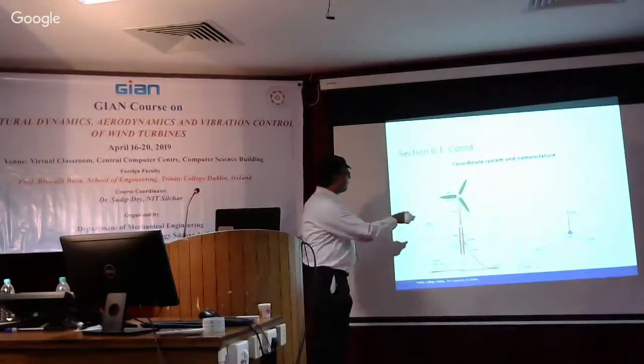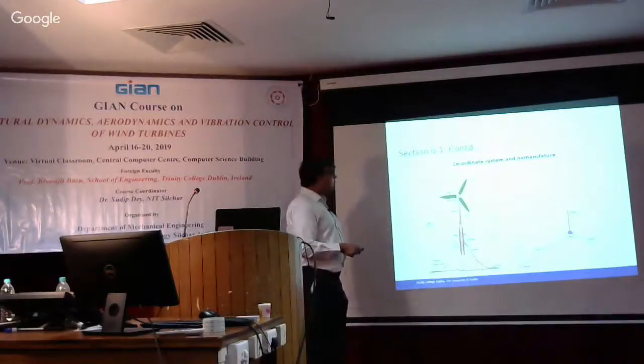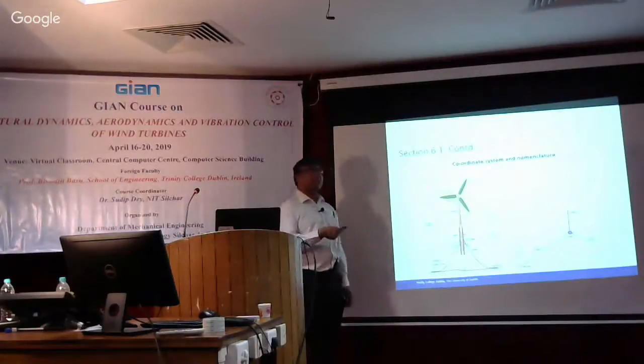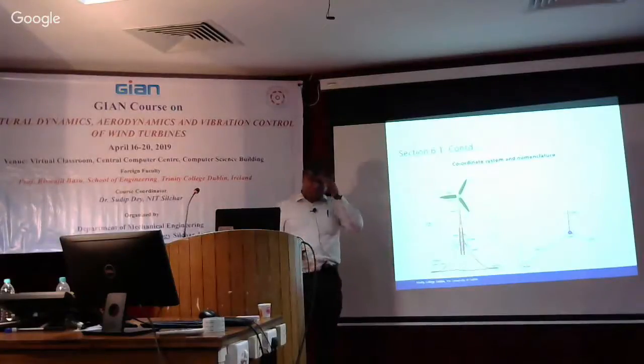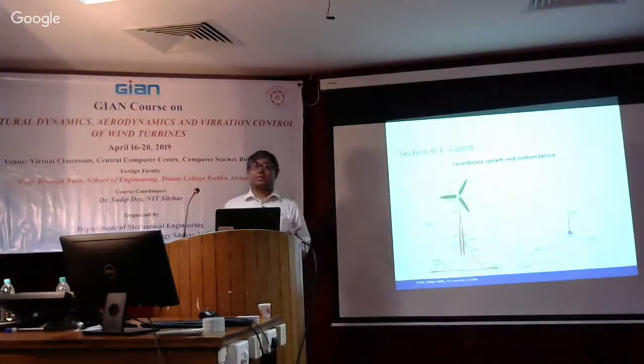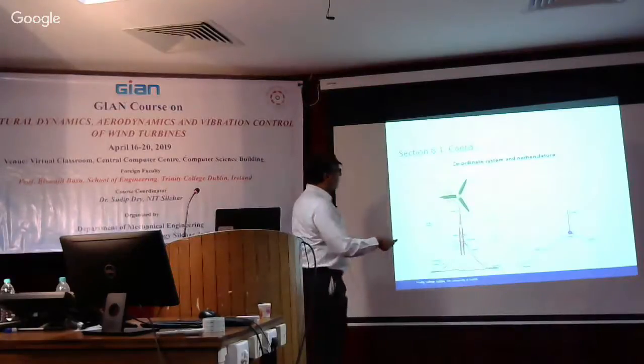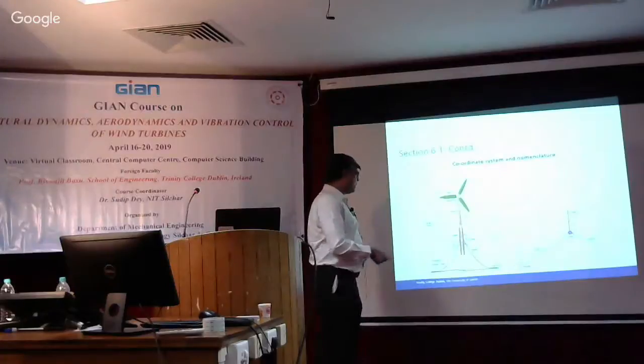So the top part you can analyze the way we have done, but now we have to add the degrees of freedom, like 3 degrees of freedom here, and change the corresponding potential and kinetic energy terms, as we did, and then apply the stationary Lagrange principle to obtain the equations of motion. There will be some additional equations of motion. And in terms of the loading, we've already discussed you have to take the wave and current loading.